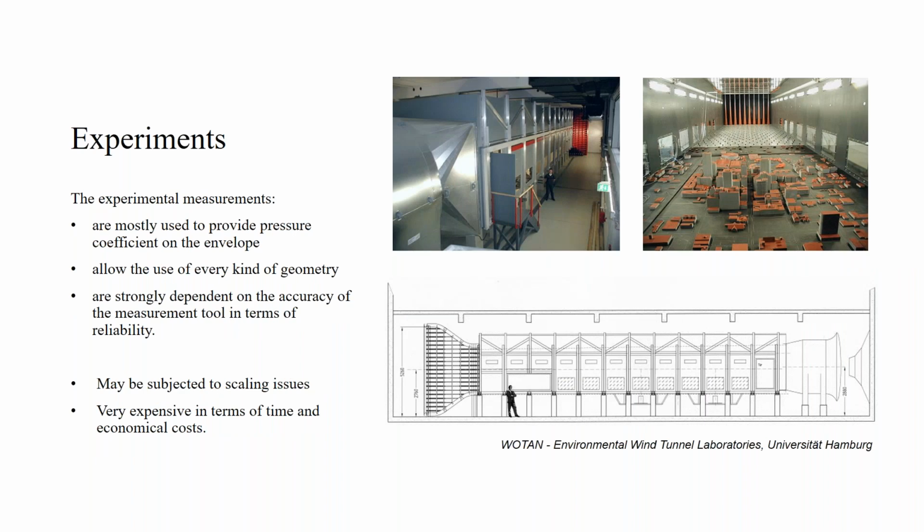I also wanted to mention wind tunnel testing, because I'm not aware of a lot of natural ventilation studies carried out in the wind tunnel, for several reasons, and I think one is scaling. But often in practice, a lot of buildings have a pressure cladding study for the facade during construction. So that's actually a good source for pressure coefficients, even if the reason for carrying it out is a different one. For odd shapes or very tall buildings, it's very frequent that these data are available, so they can be used later on in the design.